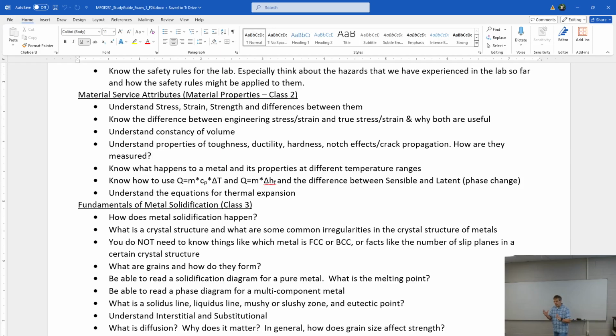And while it is physically meaningful that it's the onset of necking, numerically it is odd because we haven't been measuring the cross-sectional area, so it's not quite a real number. However, it comes up in so many properties and equations that we need to use. It's a highly relevant number, even though it's a little odd how we got there.